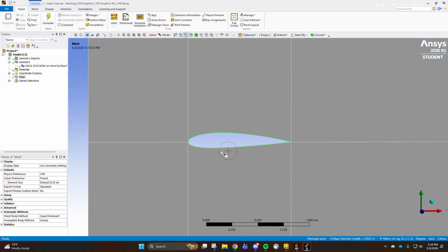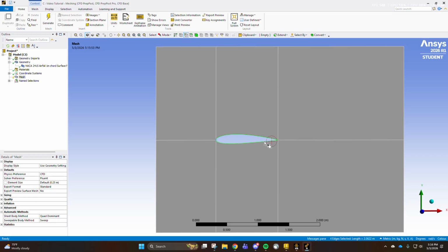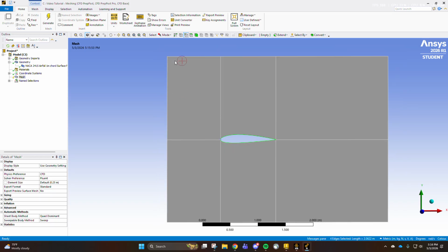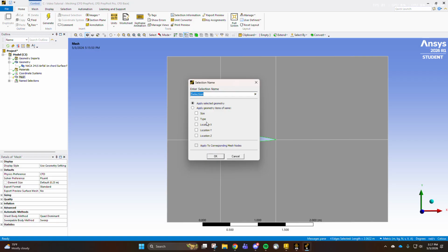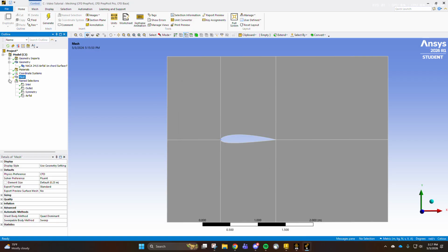There's a lot of different ways you can do this mesh. Most people will do the grid like this. Some will do a cylinder or semicircle in the front, which helps with the airfoil section expanding. But this works just as well. So this is going to be our airfoil.